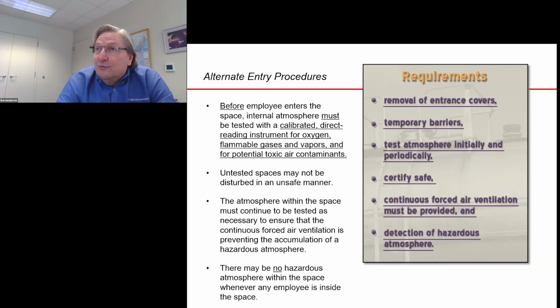So if you're going to remove the lid, you should take a sample of the atmosphere, if possible, through apertures or holes in the lid, and make sure it's safe to carefully remove the lid and not do anything irrevocable. If you sample through the lid and you find an explosive level of methane, then obviously that is not the right moment to pull the lid in a way that could cause a spark or be the source of ignition.